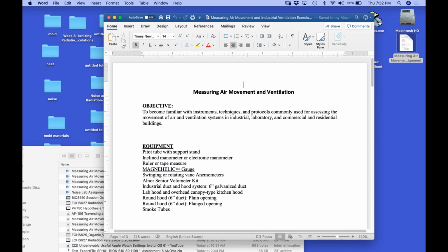So if we multiply the cross-sectional area with the velocity, what do we get? The volume, Q, is equal to the velocity times the cross-sectional area. So you have A times V, 0.196 times 1,800. That's 353.25. I think this fan is rated at 300 or 400 cubic feet per minute. You hit the nail right on the head, first shot out. The flow rate was 1,800 feet per minute.